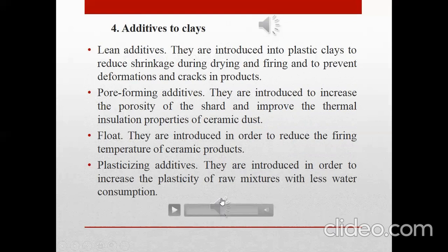Four. Additives to clays. Lean additives. They are introduced into plastic clays to reduce shrinkage during drying and firing and to prevent deformations. Pore-forming additives. They are introduced to increase the porosity of the shard and improve the thermal insulation properties of ceramic products.